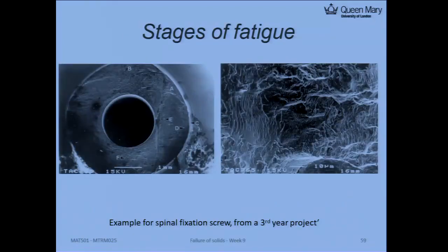So now let's just summarize the 3 stages of fatigue by using these 2 images. One is in a low magnification, one is a zoomed-in high magnification image. So if you look at the initiation point, it's roughly here. They are the initiation at the stress concentration point.